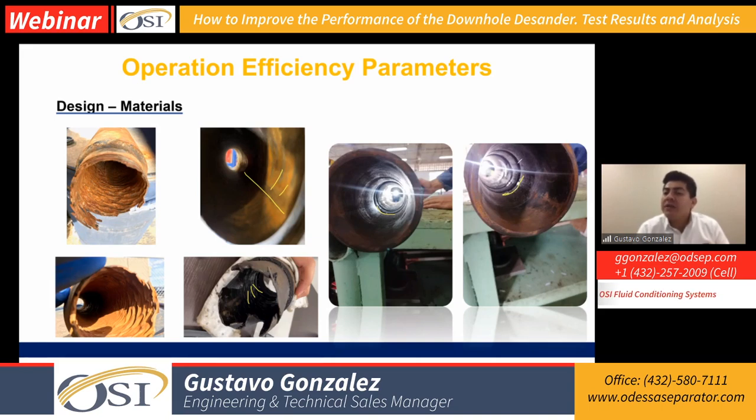So that's why we see the first mark. The higher drawdown and the fluid that was passing was pushing that wave a little further. After the well was depleted, after the first year, now that cutting out inside the sleeve was moving a couple of inches, getting closer to the helix. That is a normal phenomenon that you're going to see in any desander. A desander is designed to create that centrifugal force and start to eat some portion of the steel if you're achieving a high run life.